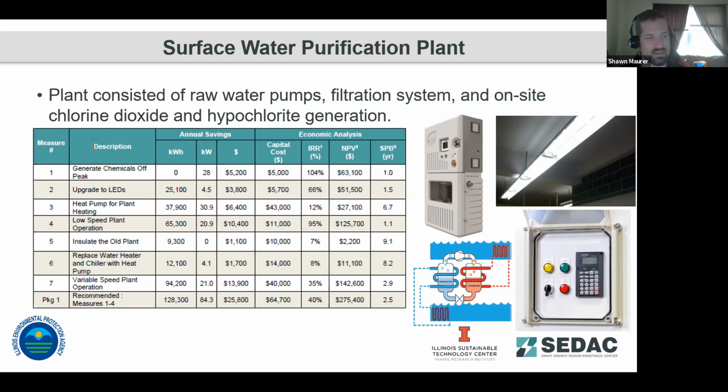If they can slow that demand period down, run those pumps at lower speed, they're saving on cycling those pumps, those numbers of starts per year, gives them some maintenance savings as well as those energy savings. And then the longer term projects, we're adding insulation to the facility, increasing the efficiency of the actual plant itself as far as the building on site.